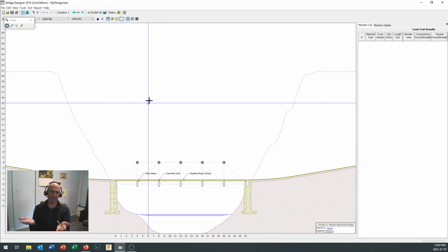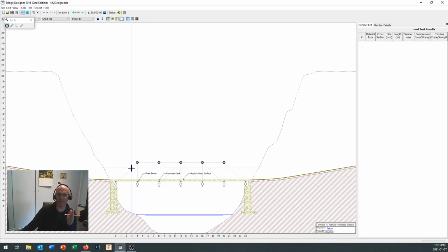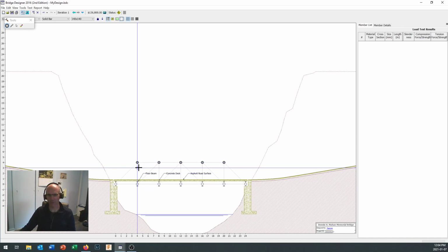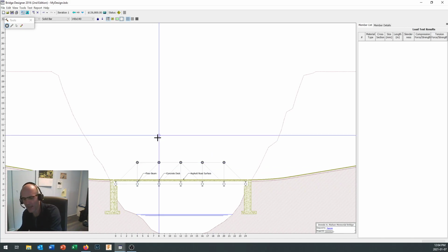In reality, it's not perfectly a pinned joint, but because these members are long and flexible relative to the load, they will flex if you don't brace and support them properly, just as if that was a pinned node. If you do your calculations assuming a pinned node, it simplifies the calculations greatly, and your actual bridge is going to be a little bit stronger than your simplified calculations would predict.